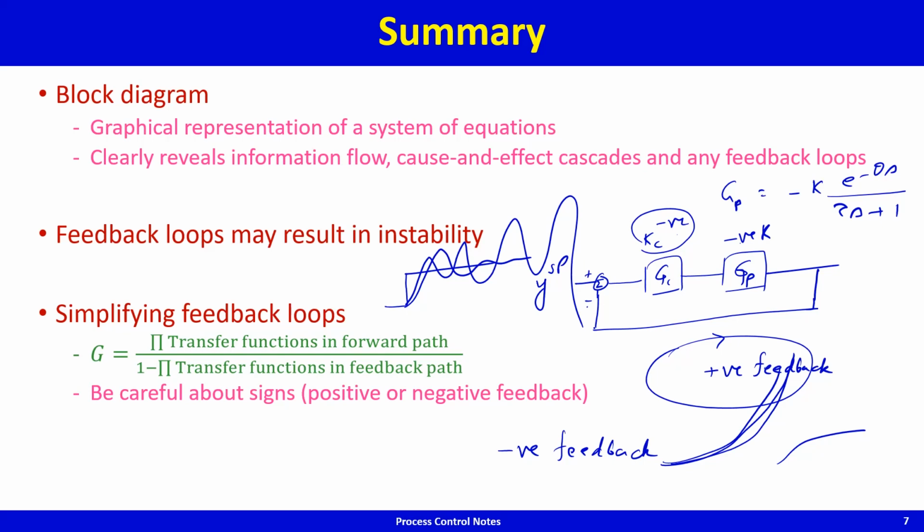So negative feedback systems will typically result in this oscillatory blow up kind of instability. Positive feedback systems will usually result in exponential blow up kind of. So this is a sign of positive feedback. And this is a sign of negative feedback, too much negative feedback. Okay, so one has to be very careful about signs when you're doing controls, because inadvertently you do not want to end up in a positive feedback loop. You must ensure that the overall sense of the feedback is negative.